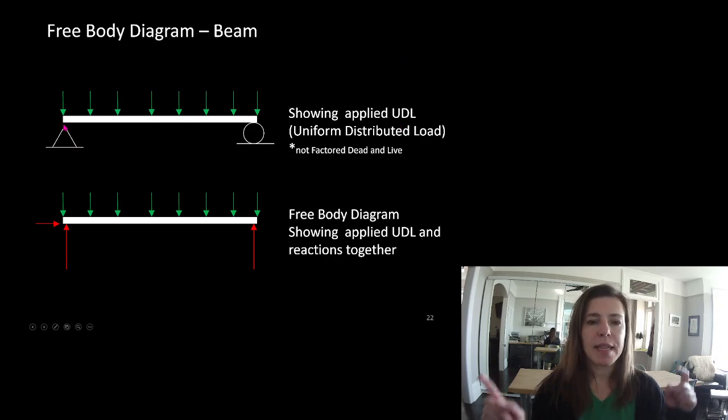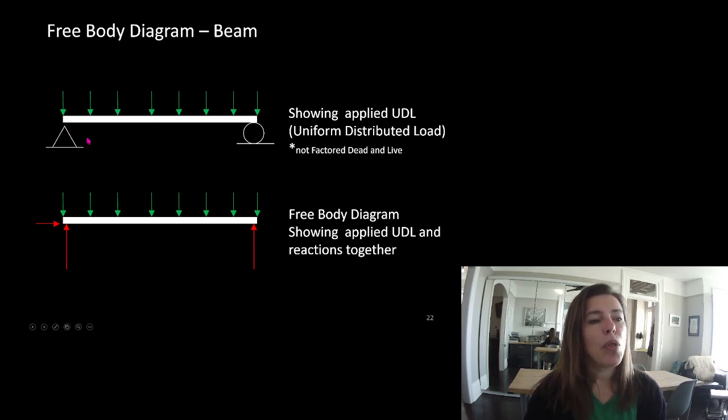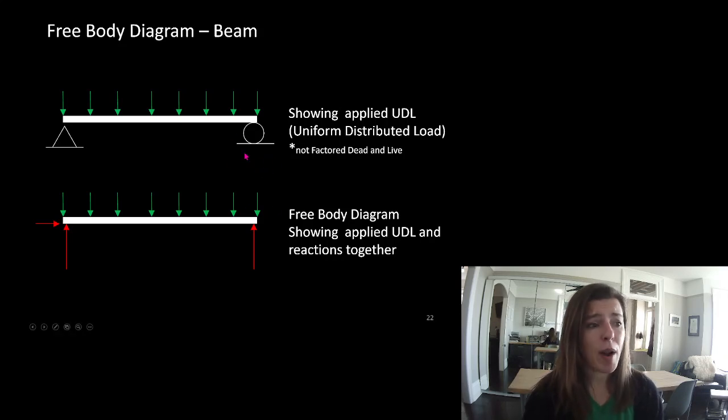So we have this beam that's supported at two ends. One end can move back and forth a little bit and the other one can't. And there are no moment connections anywhere. The free body diagram of this object, we know a pin stops things from going up and down and sliding back and forth. So we can represent this as two arrows that would be the reaction. So here's the arrow that's stopping it from going down into the center of the earth, and here's the arrow that stops it from sliding back and forth. Our roller support, we know a roller, we were told, only stops things from going up and down. So we can represent that with this reaction arrow as well. So this would be the free body diagram of this object.